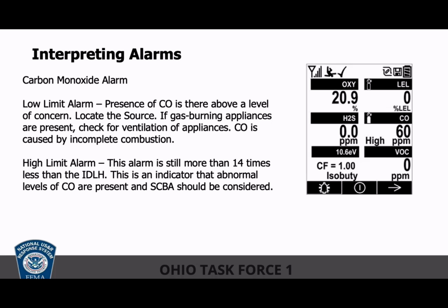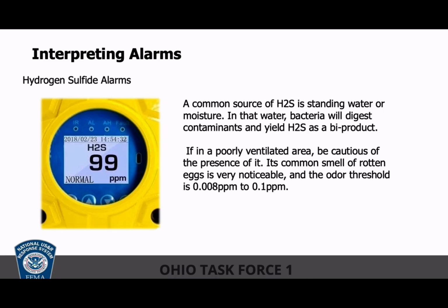H2S alarms are very uncommon by themselves. H2S has a lot of cross sensitivities. So when you're using things like MultiRAEs or Dragers or Industrial Scientifics or RKIs or Blacklines, look at the literature and see what the common cross sensitivities are for their electrochemical sensors, because it may not be H2S, it may be something similar to it.